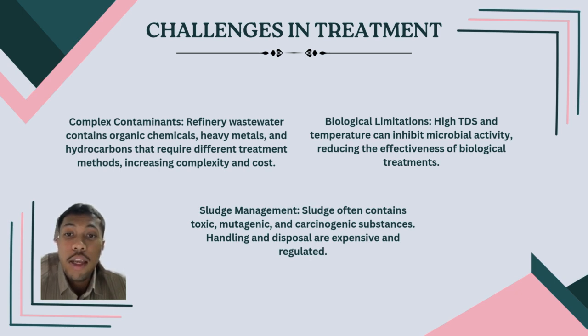As for the second challenge, it is regarding biological treatment. Biological treatment is one of the methods used in wastewater treatment. However, this could become a challenge if the chemicals affect the TDS level. What do we mean by TDS? Some refineries contain a high level of TDS, which can be harmful to the microorganisms used in biological treatment.